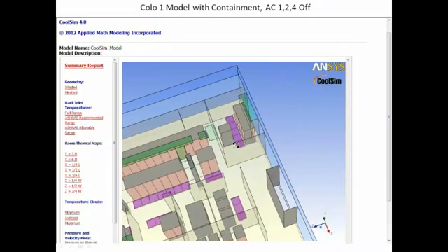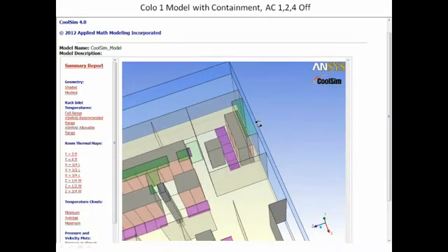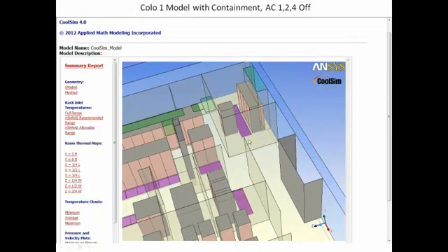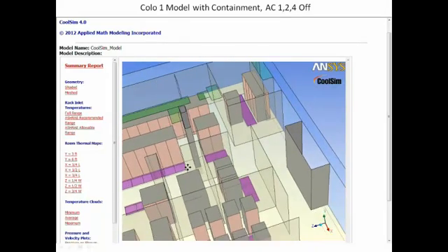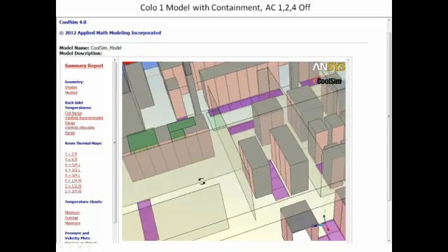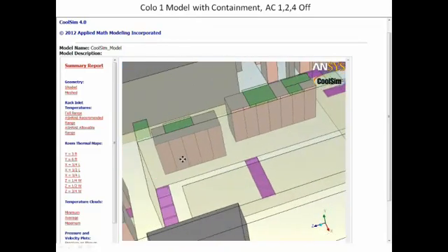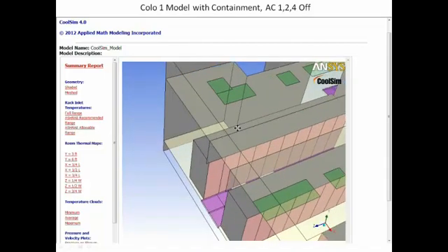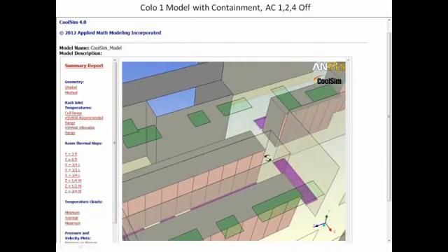You'll see over here, Liz, that I added just a little bit of hot aisle containment. These racks were up against the wall. There was a grill right near it, so I put a curtain around it. Curtains are cheap. They're made of plastic. They have links at the top that drop in case of fire. You can usually get them by fire code. They're usually quite effective.